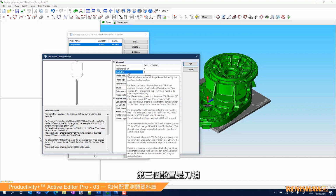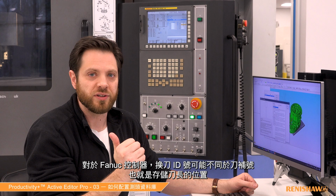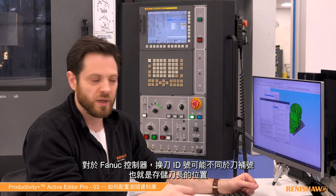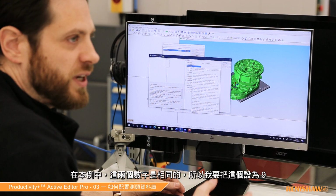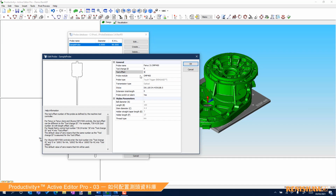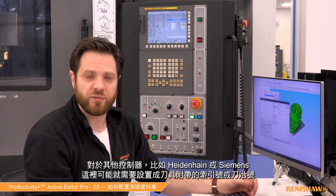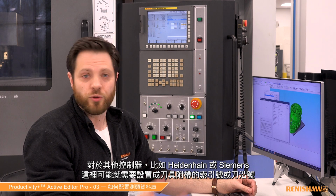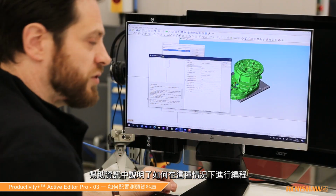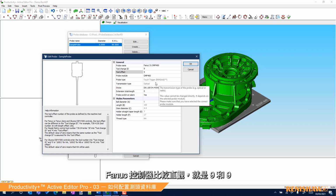So the third setting we have here is tool offset. So in the case of FANUC, it might actually be that the tool change ID differs from the tool offset location where the length of the probe would be stored. Now, that depends on what's going on your machine. In this case, it is the same number, so I can set this as 9. In the case of other controls, so something like Heidenhain, for example, or even Siemens, you might have an index or an edge number that goes with that tool. So there are some instructions in the help of how to program that. In this particular case, FANUC, fairly straightforward, we have 9 and 9.